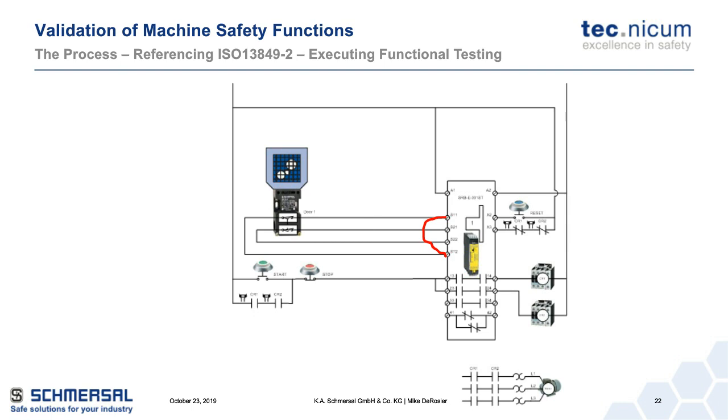And here's where you can get into your validation by design in conjunction with functional testing, because by pulling the information from the contactor manufacturer that claims that it meets this certain IEC particular number for being mechanically linked, this is rated for safety applications. Combining that with your validation report says we are simulating a failure by doing this to make sure that that is being monitored, but an actual weld of contact, if it were to occur, this is what we're getting from the manufacturer's information and test data and things like that. So we're combining the two as a result.